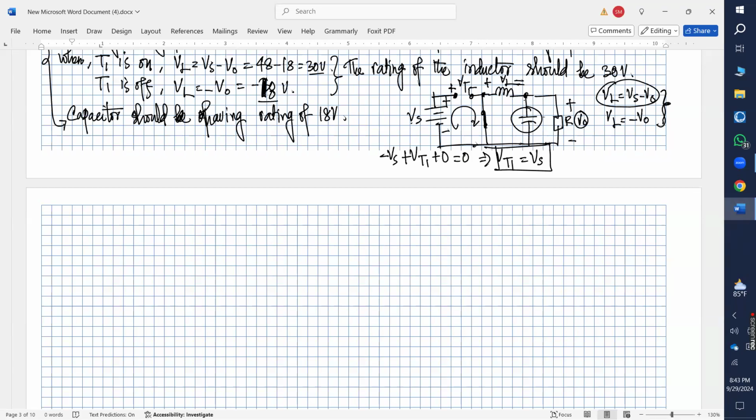So now, as you know, the inductor current will be like this, right? It will be jumping and going down, again jumping and going down, and it should have an average value, IL average, and that should be equal to my I naught. We discussed that in the previous class, right? Yes, sir.